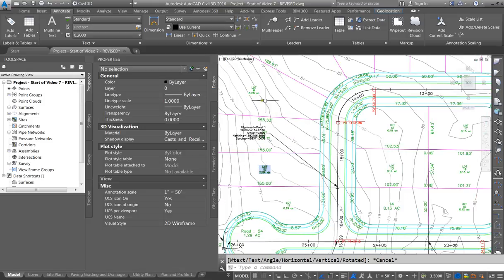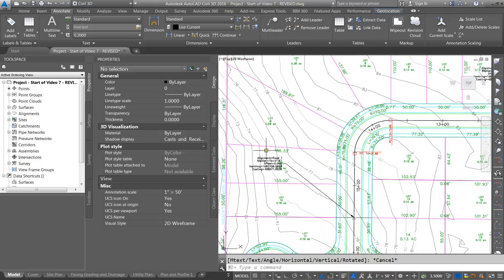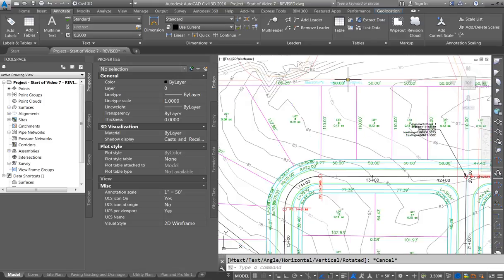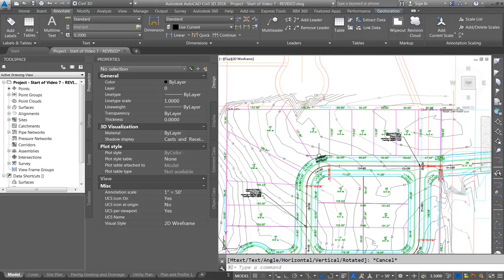So I've got 155. Again, the center line needs to be, or usually, sometimes they say at the offset line, the front offset, which ours is 20, has to be a minimum of 50 feet. So that's somewhere we'll be looking at. 50, 50, 50. All right, so it looks like all of our lots are set in proper size.